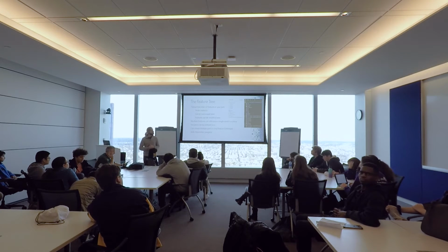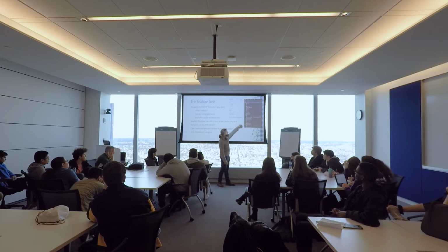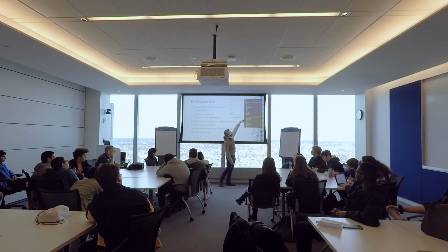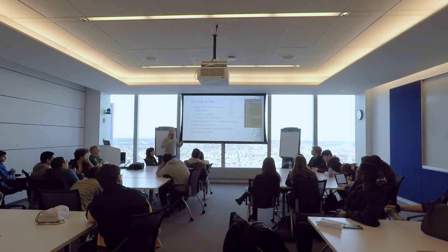So the order matters. Now the cool thing about this feature tree is these things can be reordered. Let's say I have a fillet or a chamfer up here, but I added more parts further down the list and wanted to fillet or chamfer them too. I can click and drag that down to after I made those features, literally just pull it down, and add those fillets and chamfers to the parts that were made after the fact. That's a way to keep the number of features in your feature tree low, which should be a goal as you're modeling.